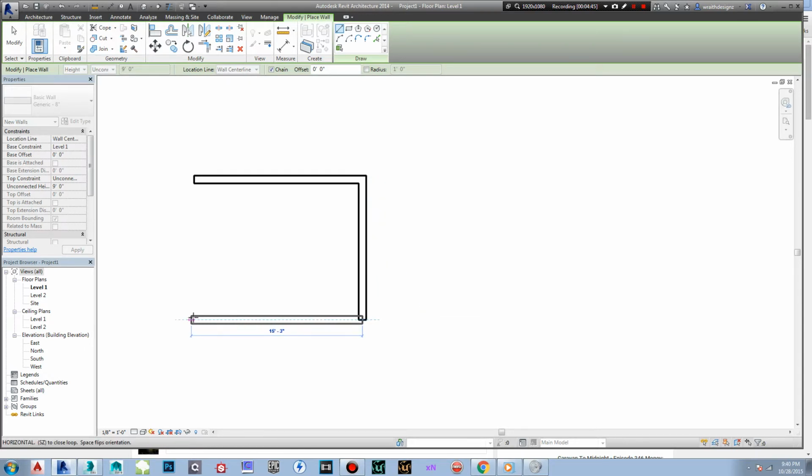Now see, when I get closer to the other edge, it will automatically draw a dotted line to show you that you are now basically lined up with the other wall. So I'm going to click again. It'll show you 12 feet exactly until you reconnect. Now, I could do crazy stuff if I wanted to, but we're not going to do that right now. We're just going to connect the wall. Automatically, it's connected. Once you seal a wall, it will stop making other walls, so it figures, all right, you're done doing that.